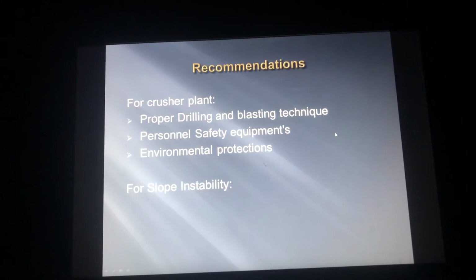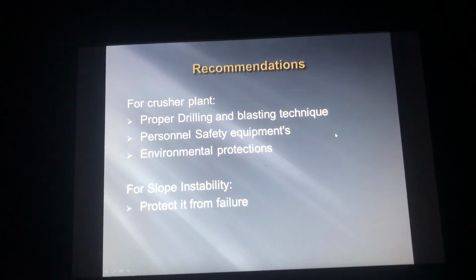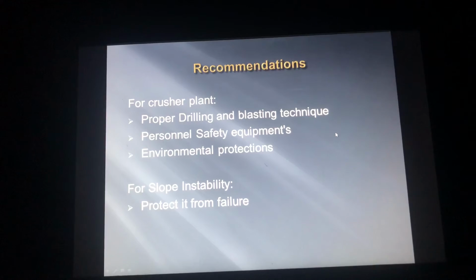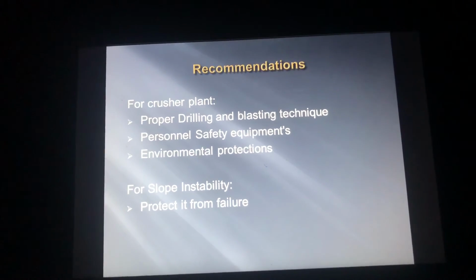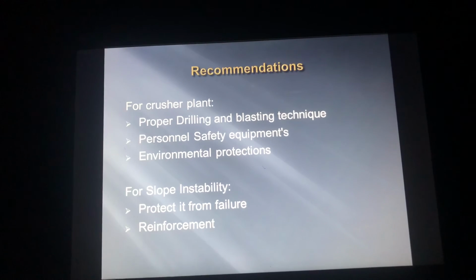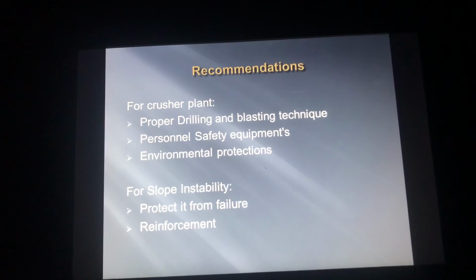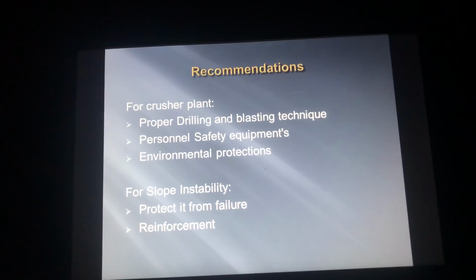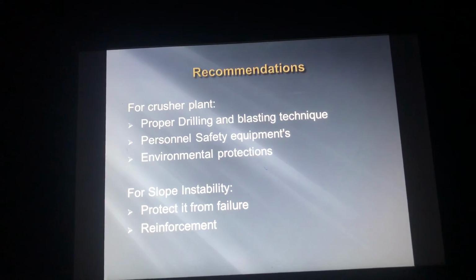For slope instability, first, protect it from failure. We can protect it from failure by draining the water, by proofing it from rain, etc. These are the approaches, and if the failure doesn't stop, then reinforce it by using rock bolts, dowels, shear keys, etc. So this is all from here.